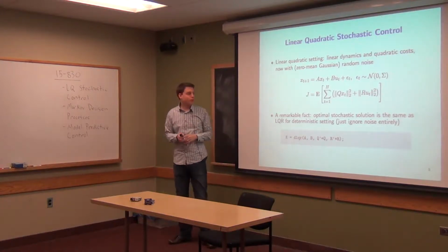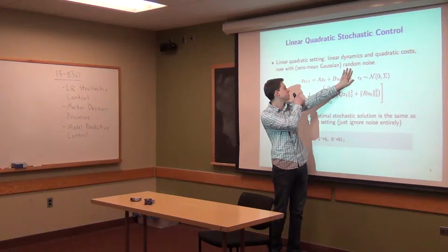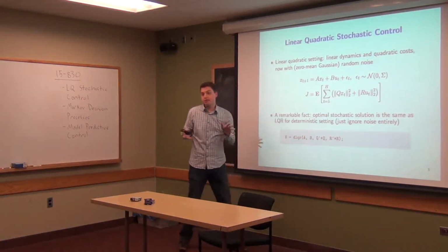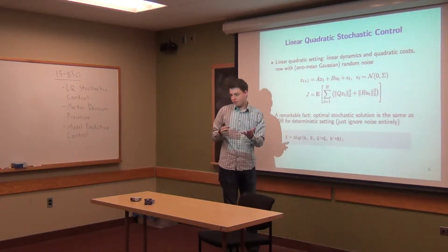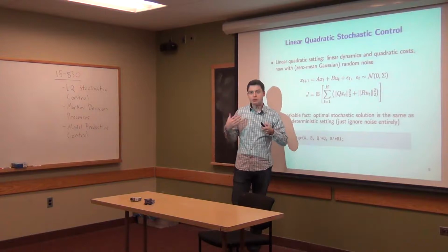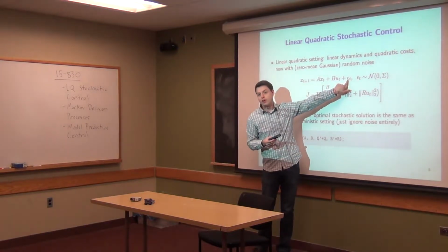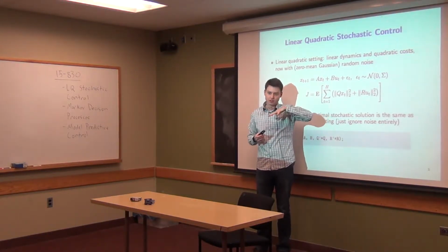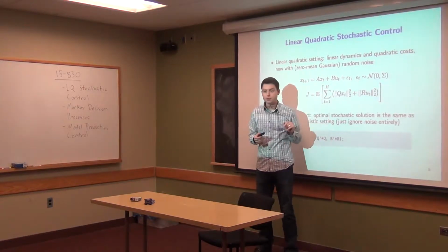But unlike before, where it was just deterministically equal to Ax + Bu, in our new setting we now have some noise. In particular, we have Gaussian noise, which I talked about a little bit before. Basically, Gaussian noise is a generalization of single-variate Gaussian random variables to the multivariate case, where you take a whole bunch of single random Gaussian variables, multiply them by some matrix, and that gives you a new variable epsilon_t.